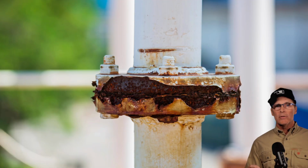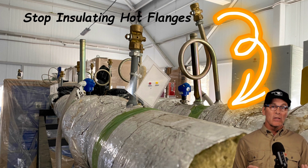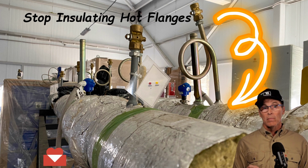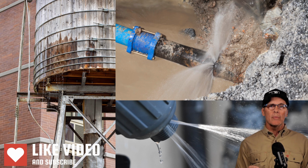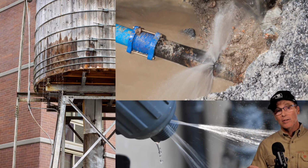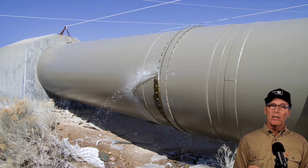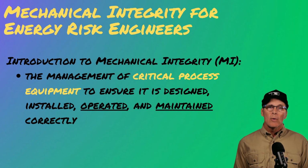We've got pipes rusting and flanges coming apart. Some of the reason that your flanges might be leaking is you're insulating them. So be careful if they're hot flanges that you look into that specifically before you go ahead and insulate them. Just some more leaks. We've got to be careful about what we're doing in our process. Fortunately, most of this looks like water, but as we know, we have some solvents and hydrocarbons and some toxic products that we handle. So even on new equipment, we're seeing leaks, and we have to manage how we approach the entire mechanical integrity process.